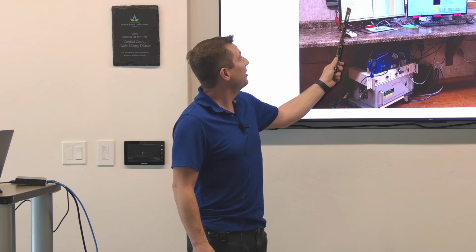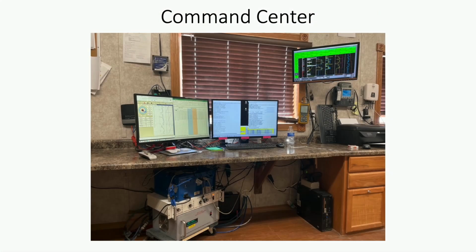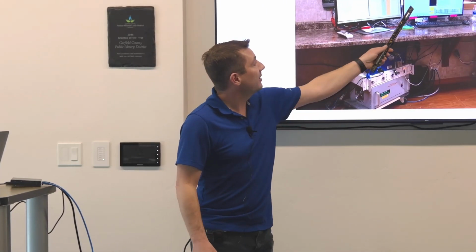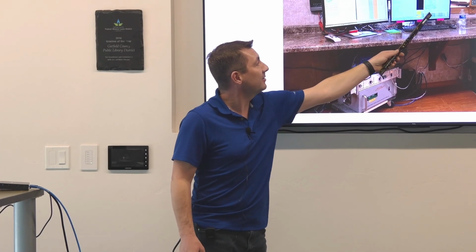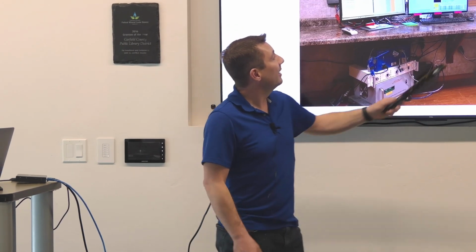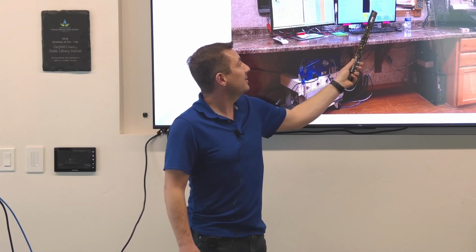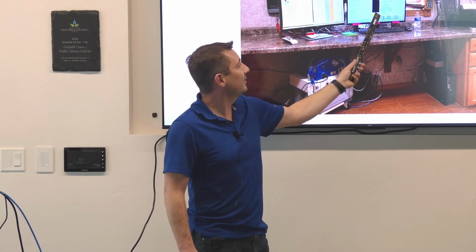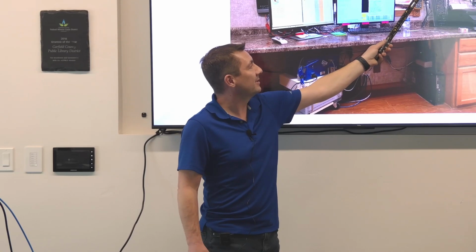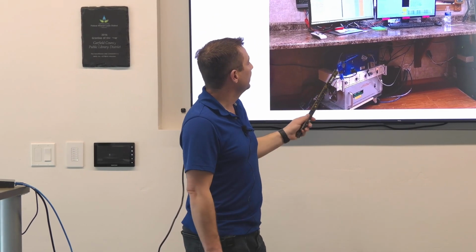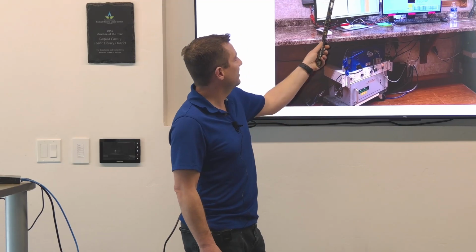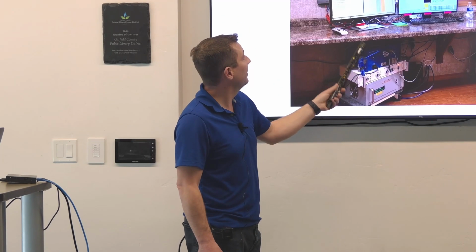This is our logging software for our gamma. So I monitor gamma, ROP, how fast we're rotating, and when and where we're making our connections. I need to know when they're getting ready to make a connection so that we're going to take a survey. You saw this software before, remote trailer and then on-site trailer software, our decoding software. I've got my O-scope so I can actively see. There's about a 2-second lag to the software's O-scope, as opposed to this, which is real time. This is the logging box for this system. All of our stuff is hooked up through that and then displayed here.